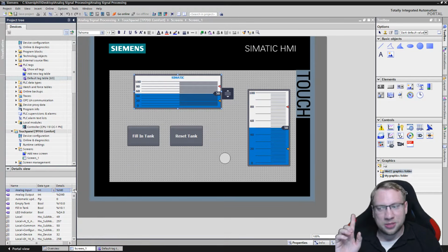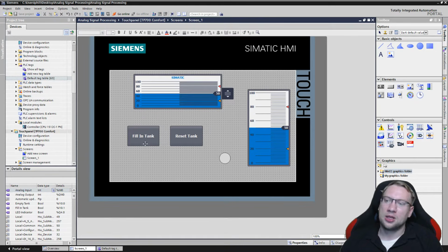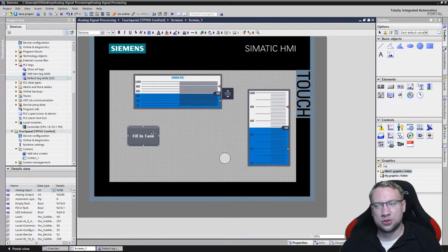So right now it's not the best practice to use the input word directly here. I would use a data block because now I'm overwriting the real physical input. That isn't too smart. Good. Let's concentrate on those first, those two. Maybe one should be a button and the other one should be this thing here, a switch. So we see as many things as possible. See this? Switch.